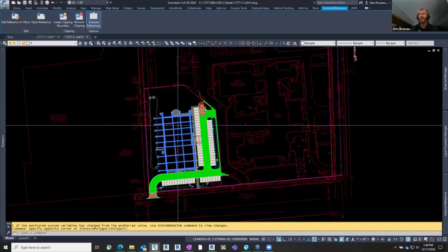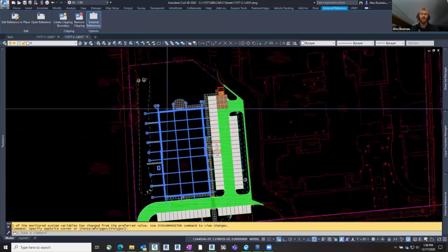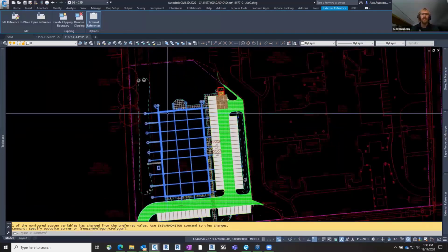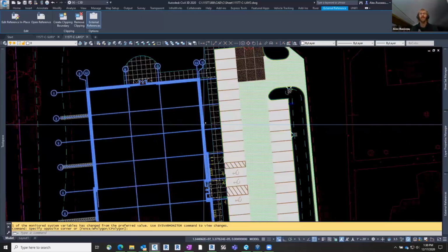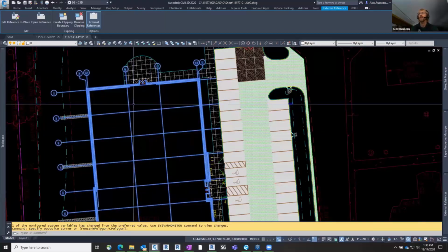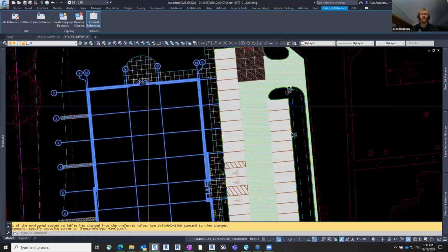And the number one thing I can always recommend: export with grids. You want your grids turned on. The reason being, as a civil engineer, the building footprint exterior looks great, but early on in the project, you've just used a generic wall. And then as you move on, you're going to start adding in brick, and then inevitably that building keeps expanding just a little bit. So having those building edges as a reference line early on is really troublesome because things expand. So grids, that's something that usually never moves. So I always like to use those in locating my model.